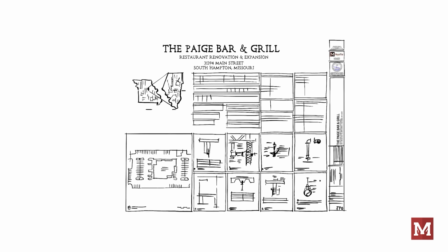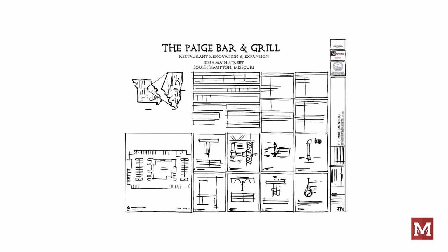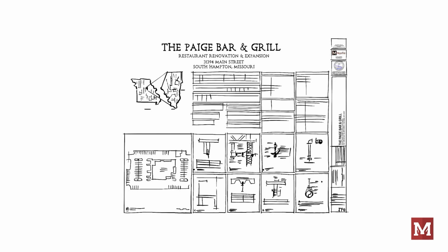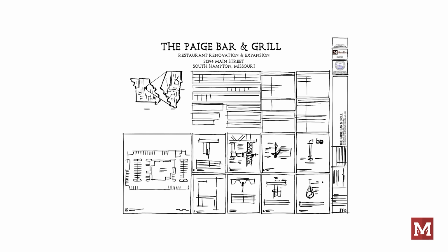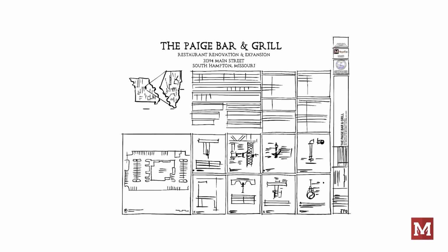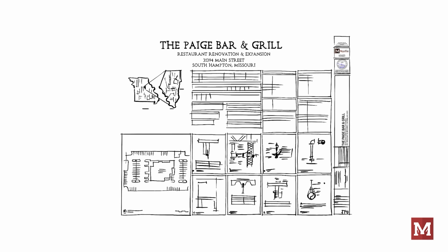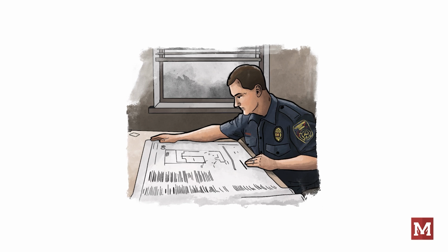During the schematic design, nothing more than a rough estimate of the demand of water and its pressure may be available. This is further refined during design development prior to the issuance of plans for construction. At each stage of the design of the system, demand is compared to the available water source in terms of its capacity and reliability. The authority having jurisdiction, AHJ, will review the final plans as part of permitting the construction of the project.